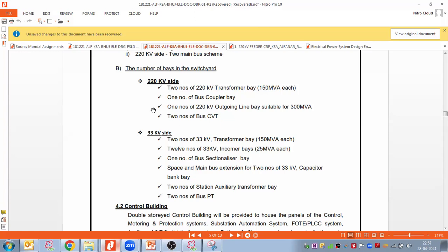In our project, we are keeping one RMU end open somewhere, and power supply is fed from both ends from the substation, bus A and bus B. So if I close that RMU in the middle somewhere, is there any problem? The power supply continues, correct? It's not a short circuit. Yeah, I don't think there is any issue with that.